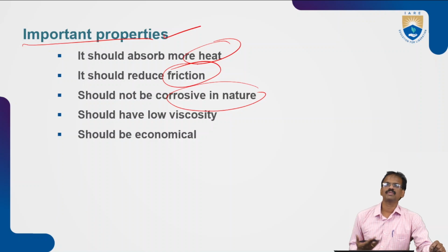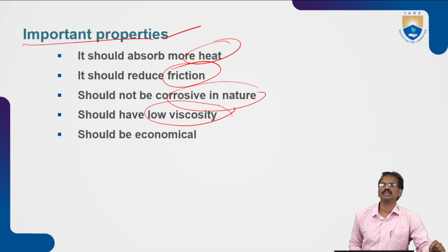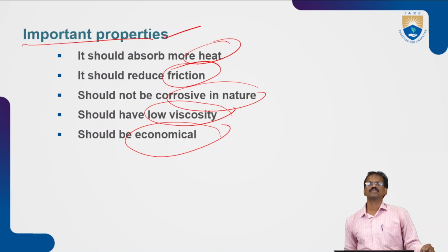So different types of cutting fluids are available in the market. We can use those cutting fluids for a non-corrosive surface finish. Next, it should have low viscosity. High viscosity fluids disturb the machining process and are inconvenient to the operator also. Next, it should be economical also. So these are the main properties of the cutting fluids.